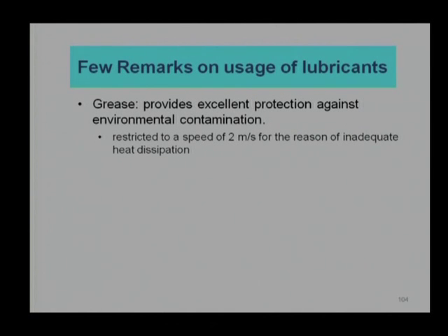There are a few remarks when we choose or use lubricants. The first remark is on the grease. The good point is that it adheres to the surface, it covers the surface. So, it gives a good protection against environmental contamination, but they are restricted to low speed applications.